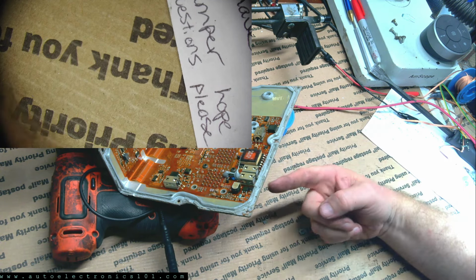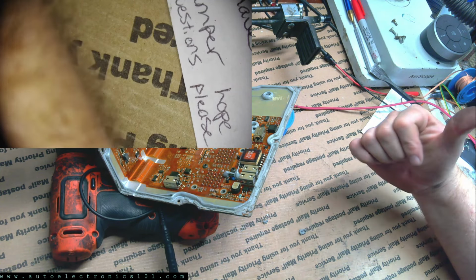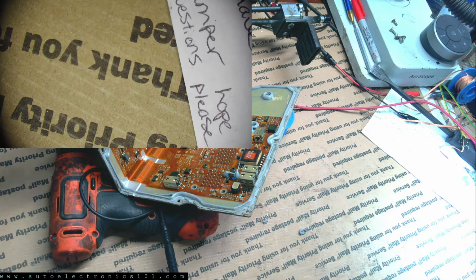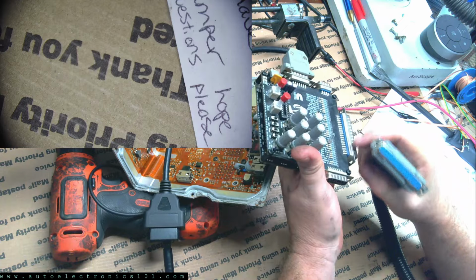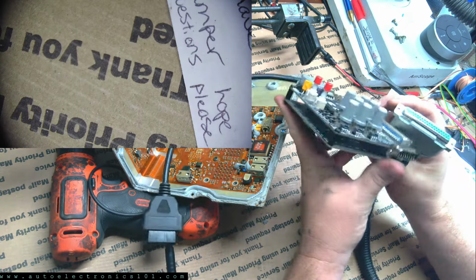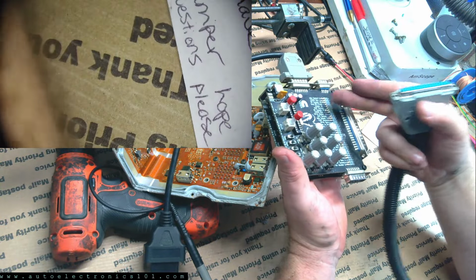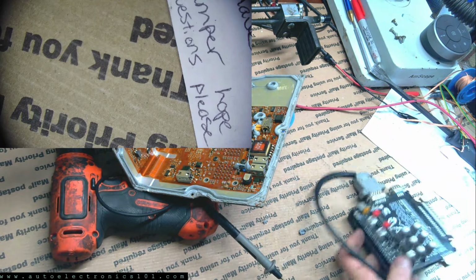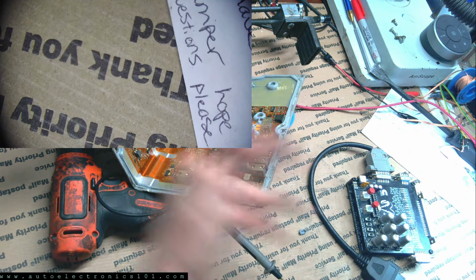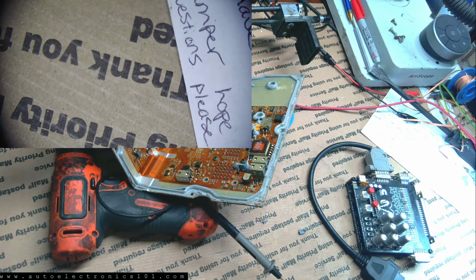I don't use the signal grounds because I was saving ports on the output, because I use a D sub connector. See, like this D sub connector, and I had to reserve spots because I filled them up. So I cut out all the sensor grounds and just internally connected it to the ground in here. And typically the ECU is built the same way. All the sensor grounds are connected together. And this one would be if it wasn't burn open. But let's just verify that by checking